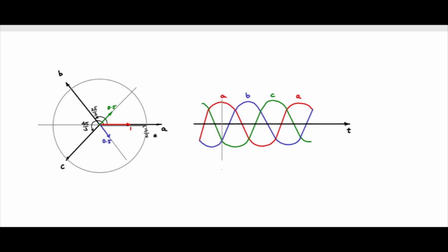Observe that along this I have a resultant vector in this direction, and then let us say I shift the time, and at this point C is maximum negative, so it is along this line. So it will be like this, the reference resultant vector. Then if I shift to another time, here B is maximum, B is along that one, so you will see the resultant goes in that fashion, and then negative A in this direction, the resultant.